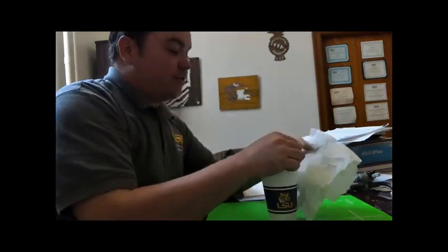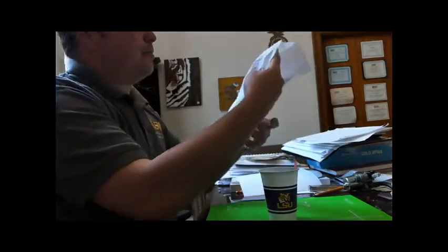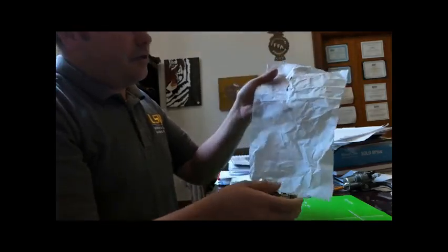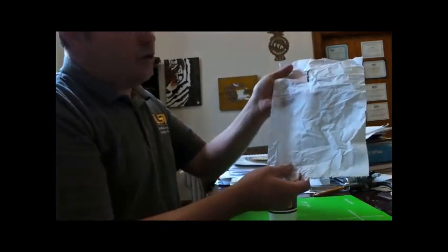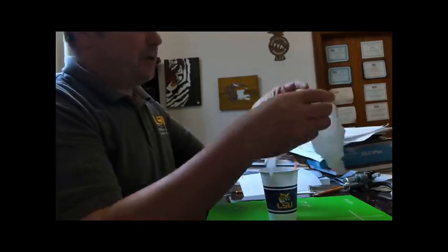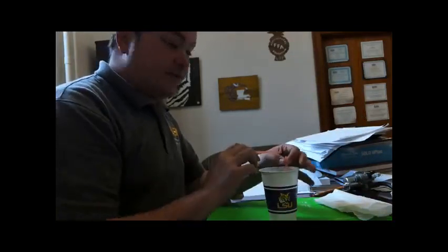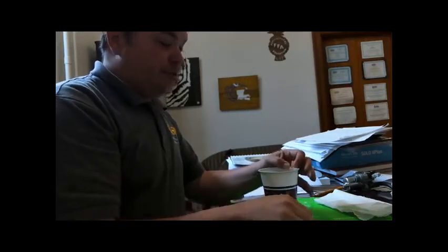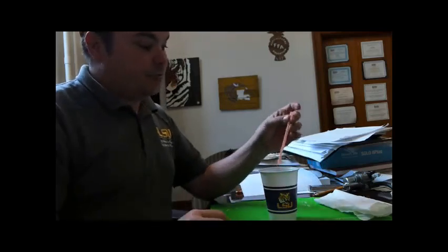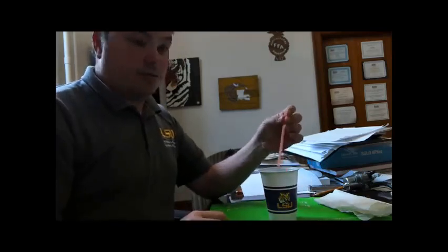All right. Not sure if you can see the vapor coming out or not, but the paper towel is most definitely wet. So we definitely utilized Bernoulli's principle to remove the water from the cup using only air pressure. So again, the increase in velocity as the air was moving faster over the straw created low pressure, and it was able to pull this water up the tube, which, I guess we could say, was representing our main jet in a carburetor.